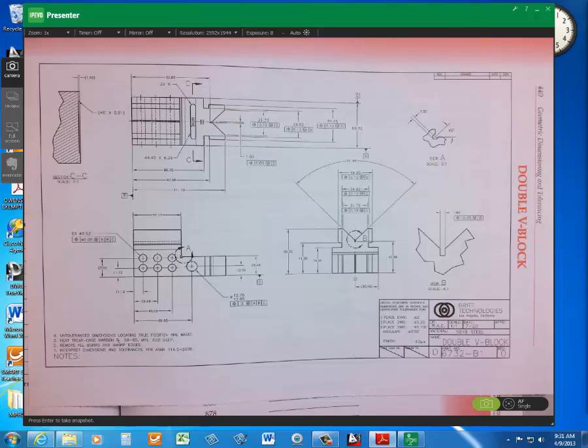It increases the surface area, so instead of the stresses all converging at one point on the beam or on the part, all the stresses in theory are at various angles to one another, spread around that surface area. You've increased the surface area, therefore spread the stress throughout the whole part more uniformly.